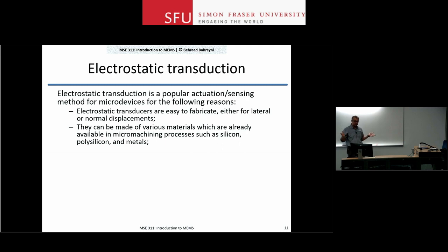In this case, we are basically talking about variations in capacitance. Capacitor values are small. The impedances of these devices are usually quite large, because remember, the impedance for a capacitor was 1 over C omega j. And therefore, the resistance of your electrodes, conductions, all those things don't matter as much.